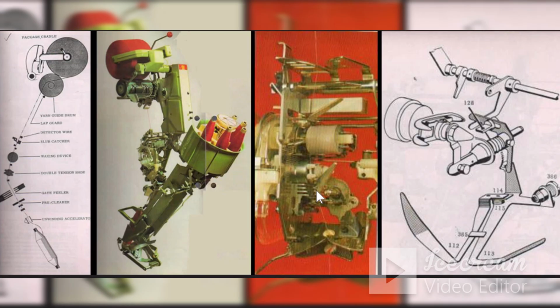So in that case, the spindle stoppage is due to yarn break and the knotter has to perform only the knotting operation. That is, the ring frame bobbin is not exhausted. So the knotter has to take the yarn from the ring frame bobbin, from the winding package, and tie the knot.